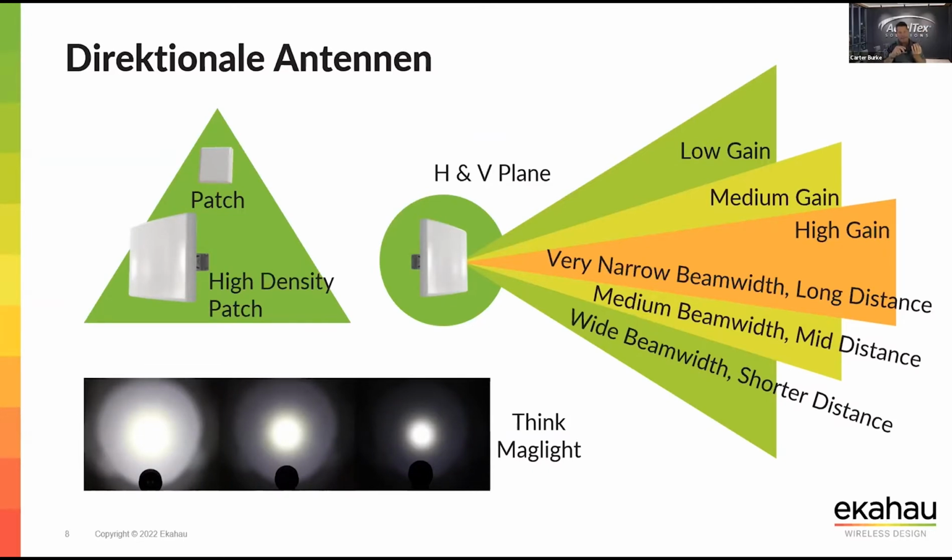As I dial down the flashlight, in this case like a mag light, it's going to get higher gain. So maybe go to 4 dBi, 6 dBi, 8 dBi, higher gain. It's going to make that pattern more focused. So think in terms of that mag light being dialed down. The same case with this antenna: if it's a higher gain antenna, it's going to give you a more focused coverage. Connor will talk about, in some of his demos, specific applications around warehousing and even manufacturing where that higher gain is important because you're trying to cover very focused areas. But maybe you don't need to cover a focused area. Maybe you're covering a very broad area. You can use a lower gain directional antenna, and that'll allow you to get that broader pattern.